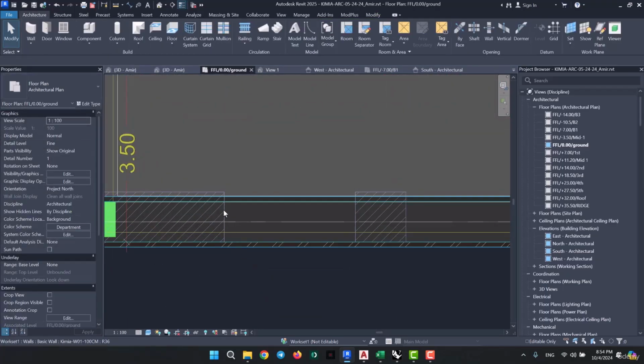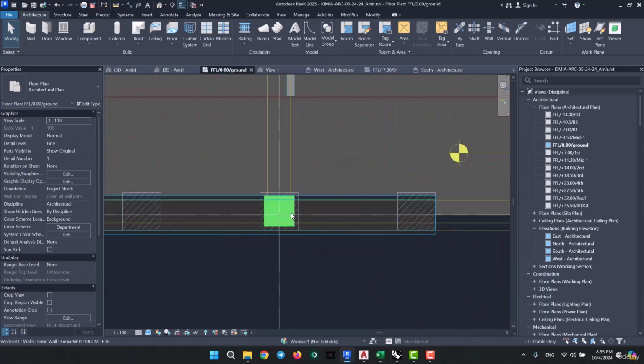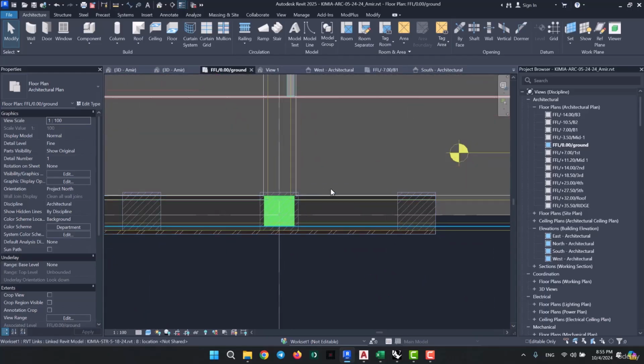Later, when I try to use the wall opening to remove this part, then the edge of the wall, which is here, will have to turn and connect to the opposite side. You probably agree because this is hollow and it has to be closed, and to cover the inside part which we've made of air material. So how can we make that happen? Do you see this one going around? On parts where you apply wall openings, your walls should have a closed end.